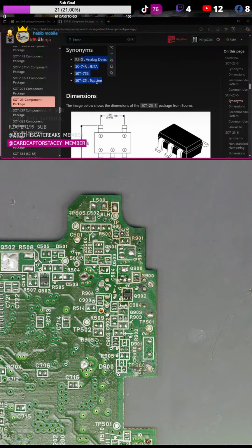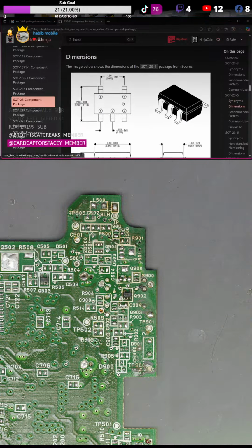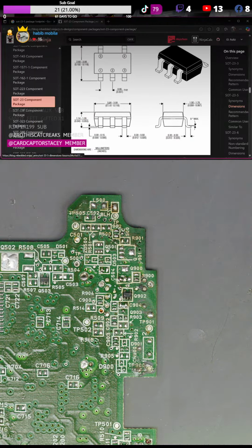Alternate names of the packages, because you can have various names. And then this is what we're interested in. So now you can see there's a width here of 0.95. So almost 1mm. So that's our vernier measurement, very much likely, just slightly out. So that adds up. So then let's measure the package, 2.8mm. Now you remember we measured 2.9. So that's the width of the actual black body.